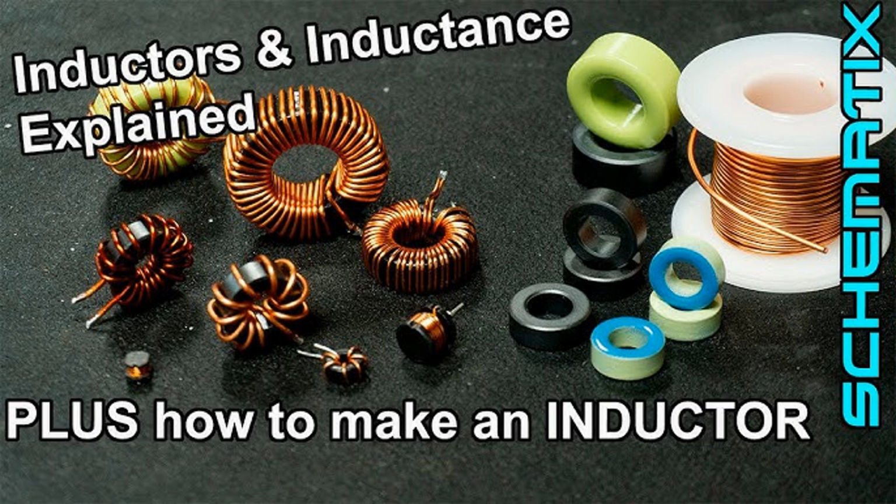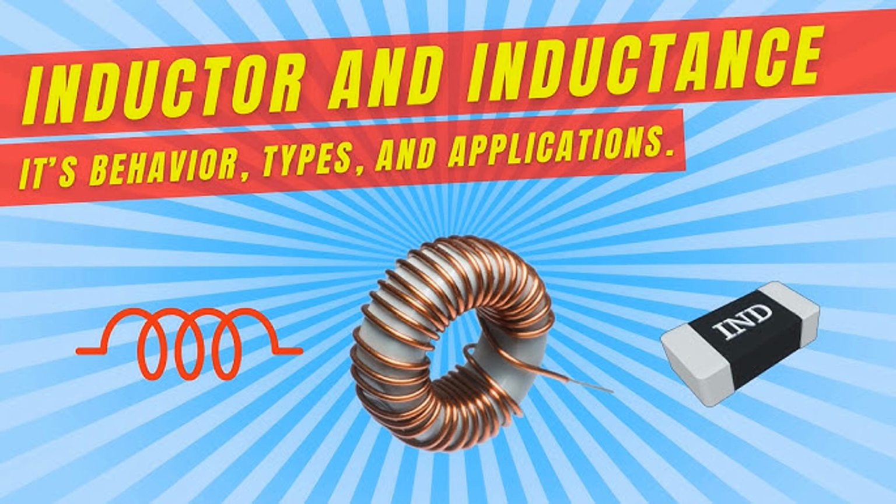Key points. Back EMF: when current changes rapidly, the inductor generates a back EMF, which opposes the change and limits the current. Gradual current change: inductors prevent sudden surges of current, allowing it to change more gradually over time, which protects components in the circuit. High efficiency: inductors can limit current with minimal power loss, as opposed to resistive methods that dissipate energy as heat.